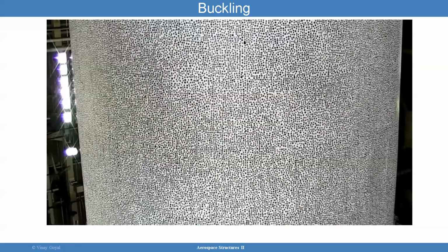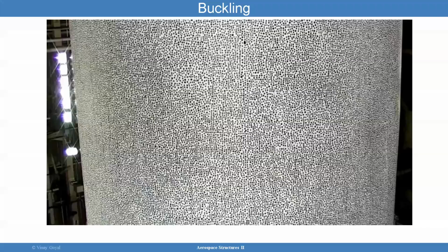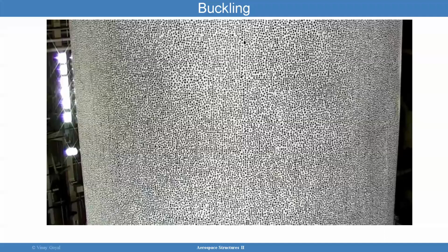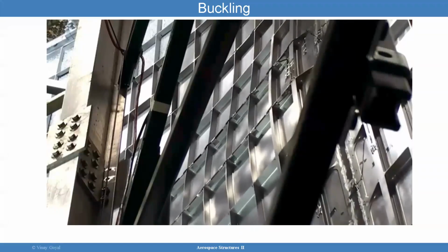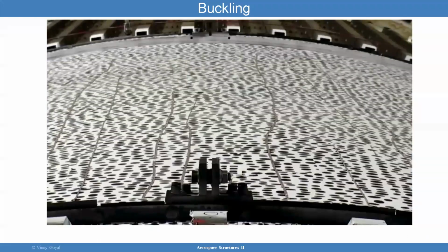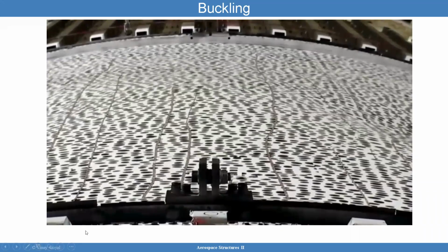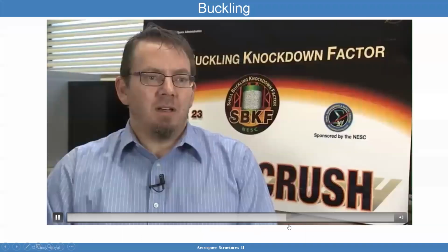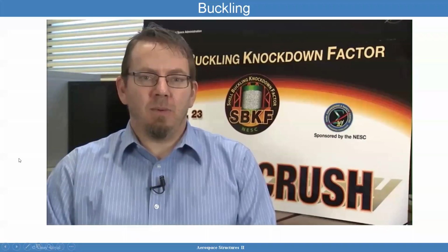Well, we had several visual cues of this thing buckling. We look at data to see that it's buckled. We have our digital image correlation data that's streaming real time for us that indicated, even before buckling was occurring, that the buckling was anticipated. But we can also view the test article outside of our control room window, and we have it positioned in such a way that we can see it buckling at the time. And so it was quite dramatic. We could see it buckle, we heard the bang.